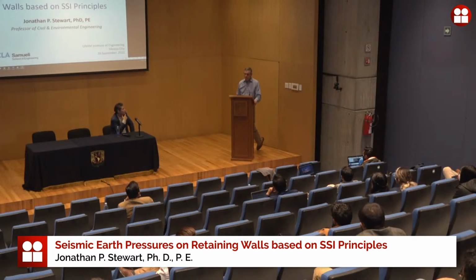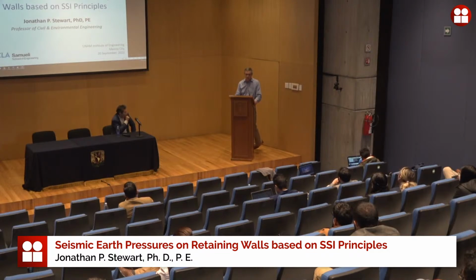The way that I would handle this in practice is I would actually start with the liquefaction problem. That is the more serious problem if you have it. So if you're worried about liquefaction, you should really do that first. And if you think your wall will become unstable as a result of liquefaction, either in the backfill or the foundation, you have to fix that first, either by improving the soil, lowering the groundwater table, or any of the typical ways that we can handle that. And once you get into a regime where you don't expect pore pressure, then I would use something like this.